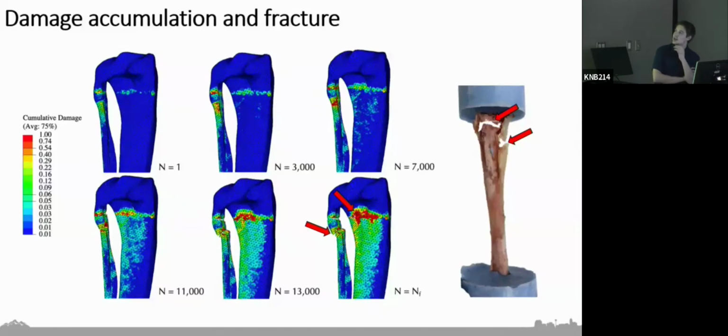Yeah, sure. I don't know that uniaxial loading would be great. You'd get a strain distribution, and maybe based on the bone quality you can get an idea of whether they may or may not be at risk of stress fracture. But I think it would be more reasonable to try to match some type of loading condition, like the running loading conditions for a female runner, because you get a different strain distribution.